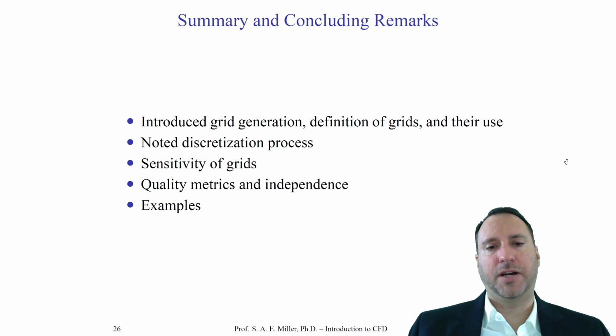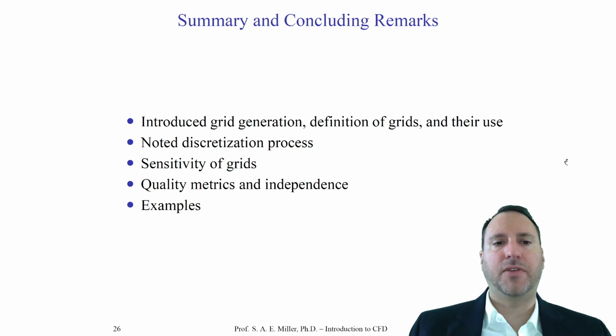We also talked about how to find grid independence and how adding more grid points in a simulation greatly increases the computational cost. It is a nonlinear cost you're paying for adding grid points, especially in 3 dimensions. Finally, we just looked at a few quick examples of what these grids might look like. But remember, you'll see many more through this class, and you can find many online that are really great.